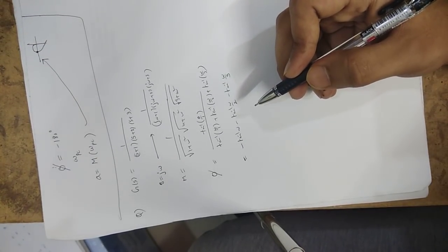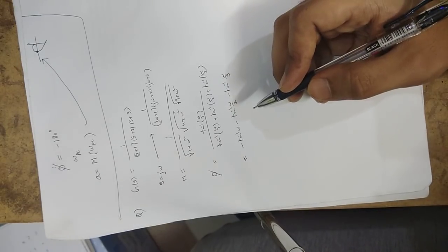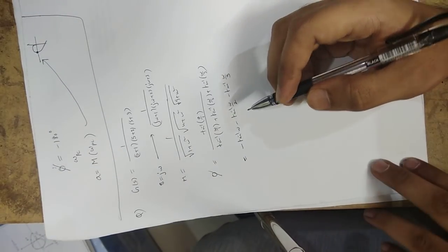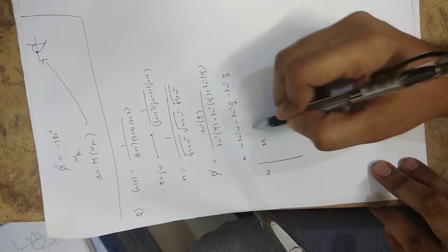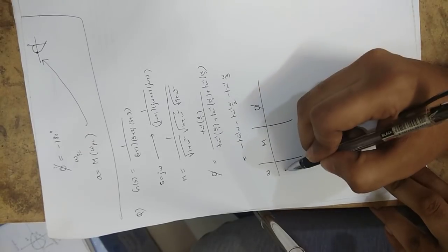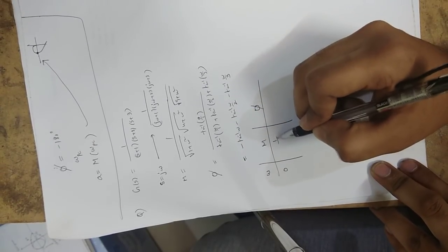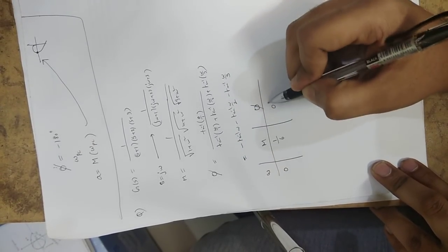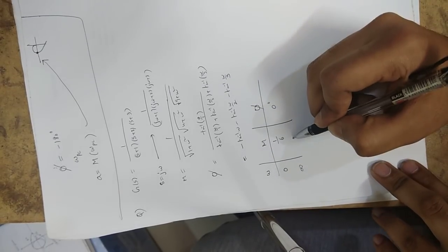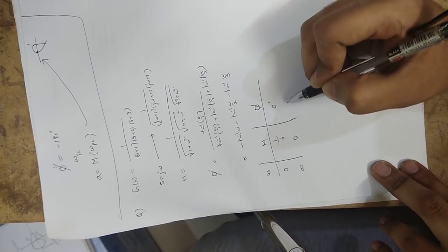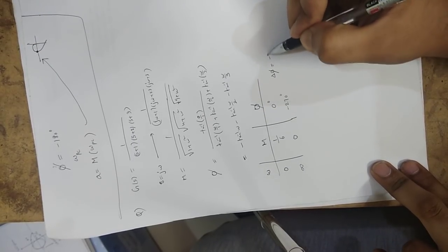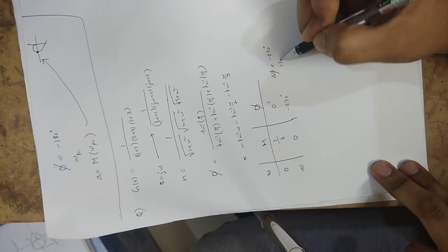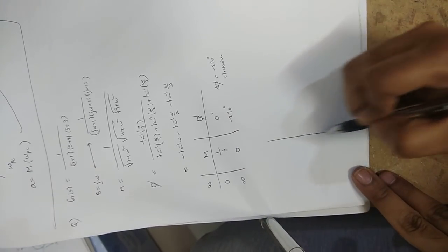Now what we need to do is similar steps, that is, vary the value of omega, find magnitude, find phase. At omega 0, you will get magnitude 1 by 6, phase 0 degrees. At omega infinity, you will get magnitude 0, phase minus 270 degrees. And delta phi, the phase difference, is minus 270 degrees, therefore the direction will be clockwise. So now draw the polar plot.